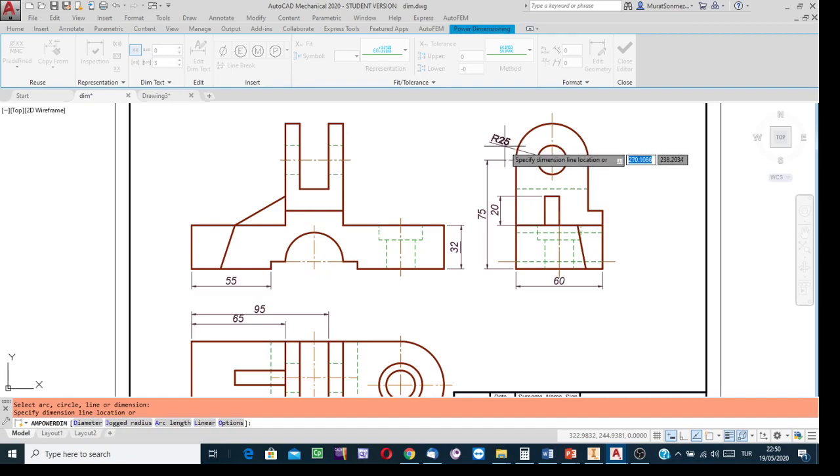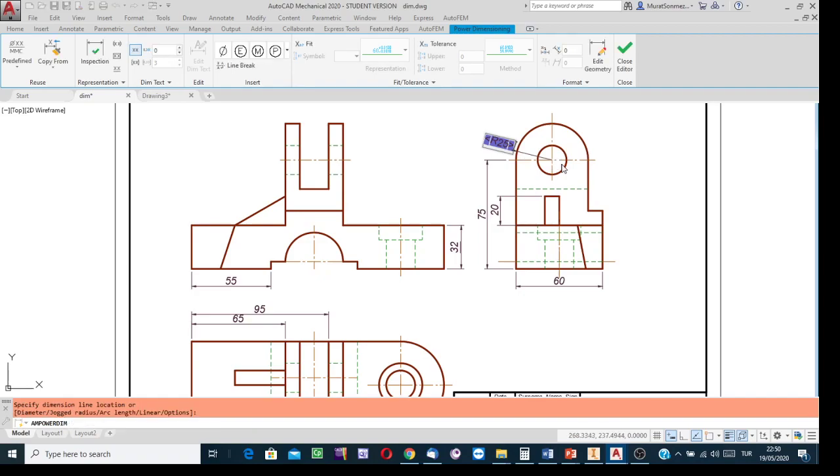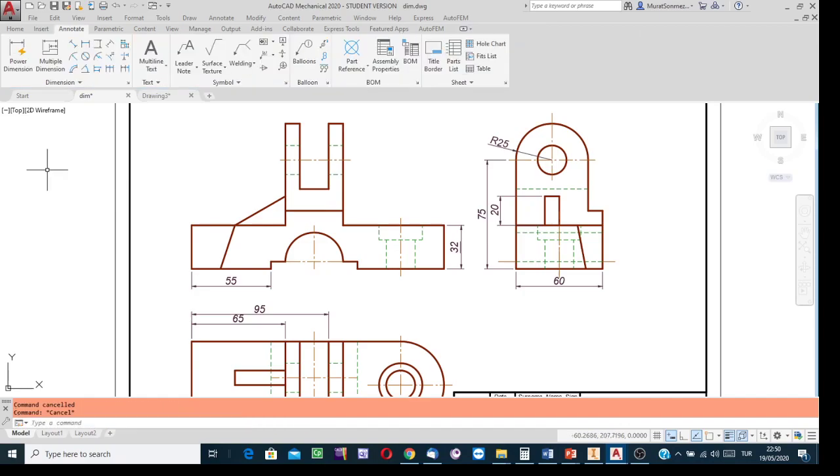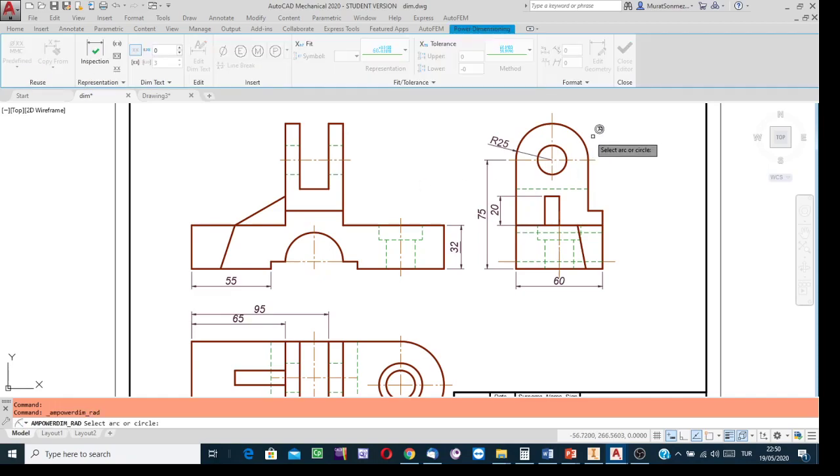As inclined, not horizontal, not vertical, but inclined. And you know the convention. For showing radii and diameters, we omit the extension lines. Press enter. Or if you say that hocam, I may forget clicking on enter key, then select this facility, click on this and then show the entity.